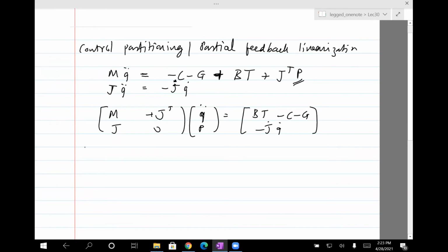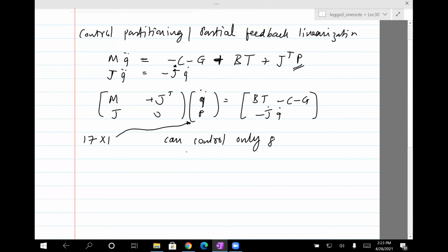So as I said, we have 17 equations really, but we can only control only 8 of them. Okay, any 8 of them can be controlled. It's your call which. And so what I decided to do is I control the absolute theta, phi, and psi, and that's only because I want to control the torso orientation, and then I need another 5 more which I can control. So I always control the knee joints. Okay, these are fixed. They always control them.